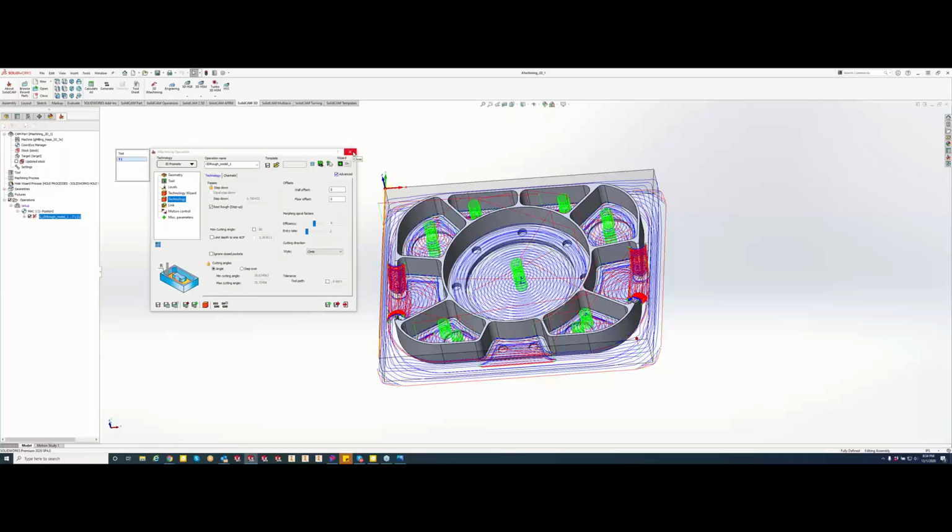One thing of note from earlier on, you were talking about selecting a model individually if you had multiple models. Just wanted to reiterate that if you're going to do that, you want to make sure that you have a working area or select all the models that are encompassed by that stock. Because if you only have one 3D model selected, it will cut all the stock up to that model. Great point. So just be aware of that when you're selecting different models.